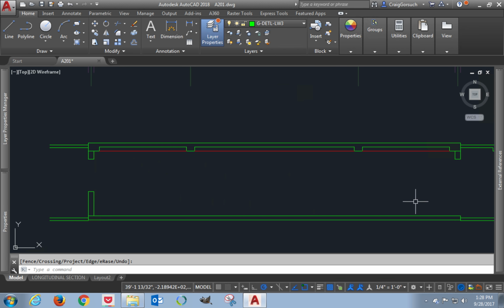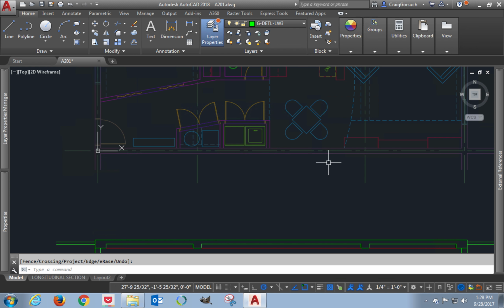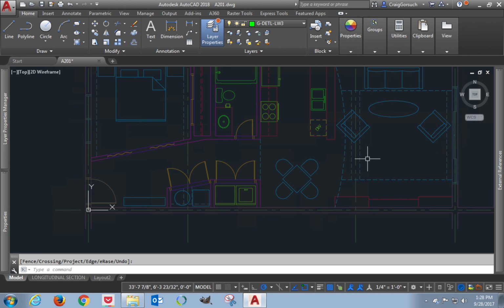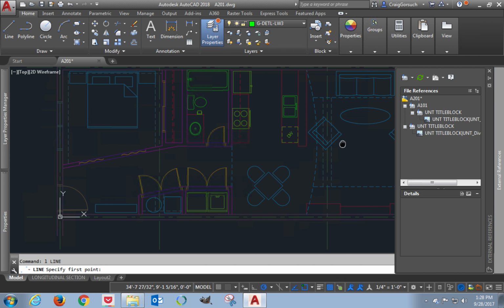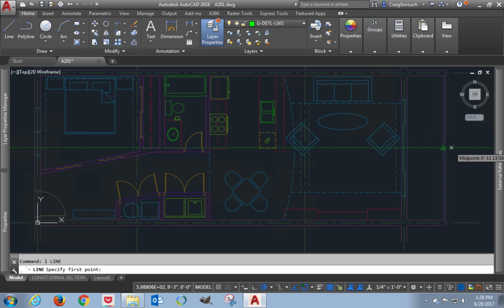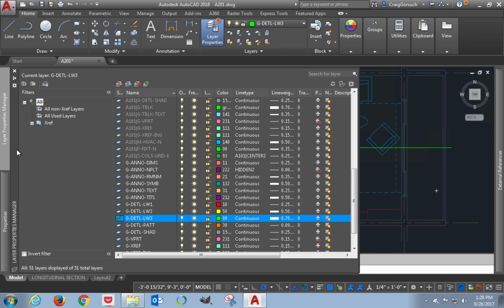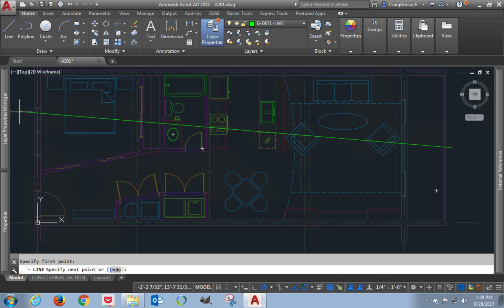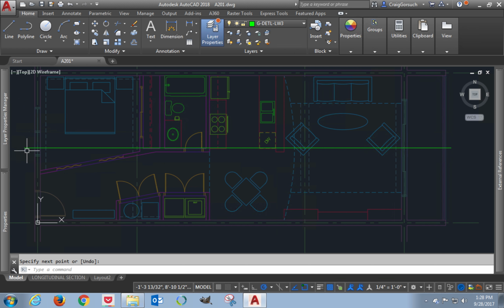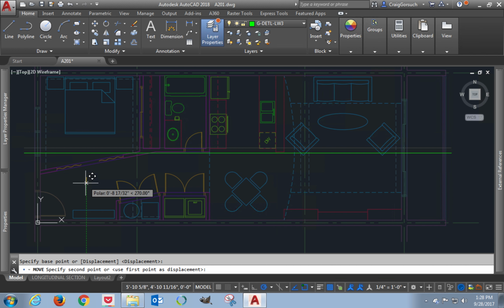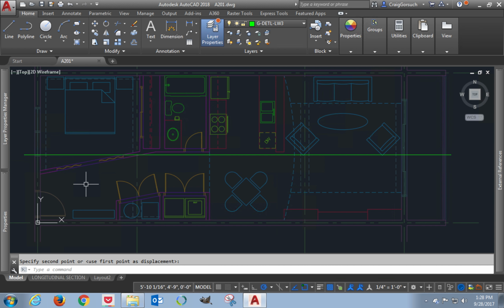One side is going to be the window, the other side is going to be the sliding doors. Now, this is the way that I can describe this. If I'm going to draw an imaginary line right through the middle of the apartment, this line, those of you who use SketchUp, I'm going to move this just ever so slightly. Those of you who are familiar with SketchUp, you know you've got that section cut tool where you can cut the model in half but only show half of it. This is kind of what we're doing, only using 2D drawings.